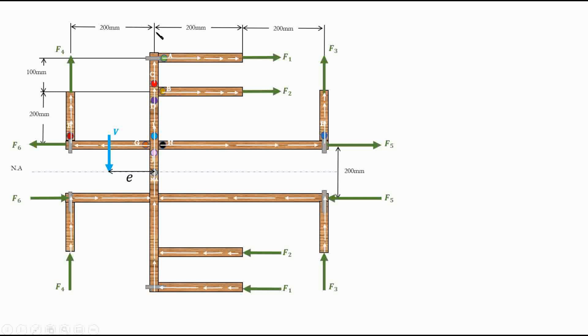However, an average calculation for that one would be very complicated, and it would in fact be very inaccurate, right? For the flange, we know it's linear, but for the web, it was parabolic. We had jumps in the shear stress distribution in the web. So it was very difficult to calculate an average value, and that would make our calculations very inaccurate. So what we do is just get rid of the force that we are required to find for the web, by saying let's take the moment about any point in the web.